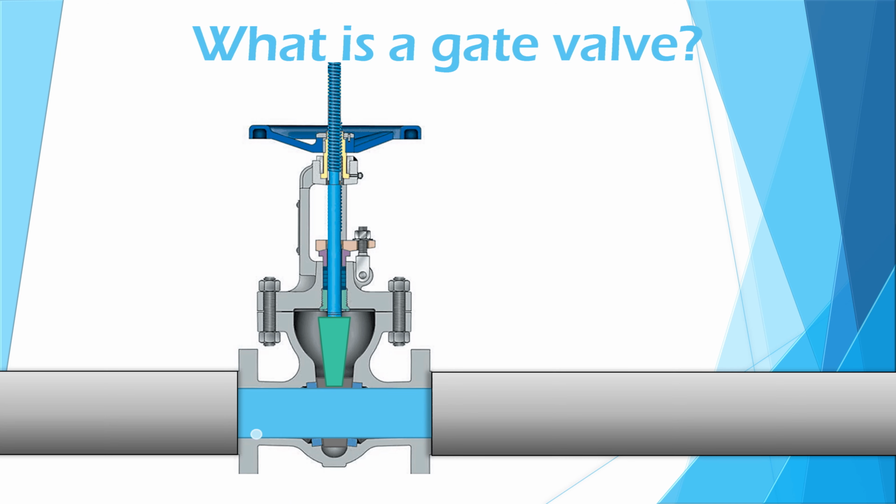The benefits of gate valves are they provide a large flow area, there is low flow resistance, they are simple in construction, and they're easy to operate. Gate valves are typically utilized in completely open or completely closed states.